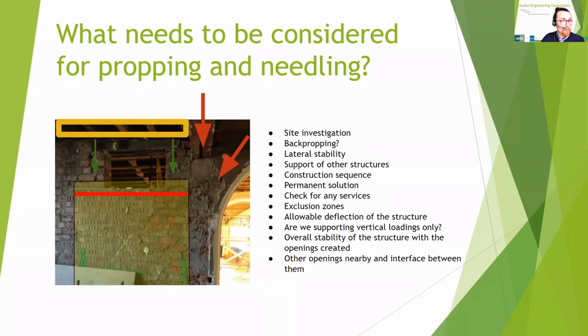Is it feasible to back prop below? The floor below may well be occupied by a third party, which would mean that we can't back prop. The lateral stability and the support of other structures: we have an arch here. Will that be supported by the needling scheme? Is this wall acting as a shear wall potentially, providing stability to the structure as a whole?